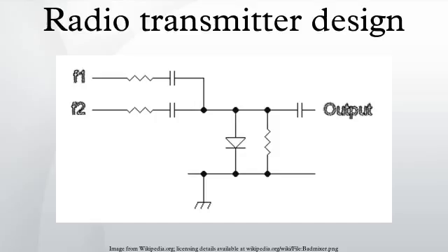If the output of an amplifier stage is simply tuned to a multiple of the frequency with which the stage is driven, the stage will give a large harmonic output. Many transmitters have used this simple approach successfully. However, these more complex circuits will do a better job.